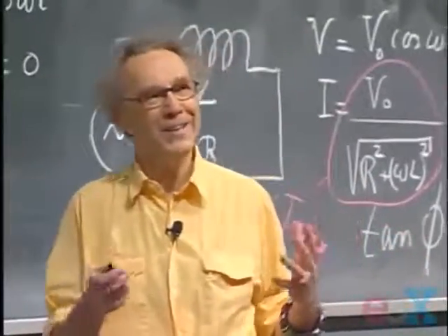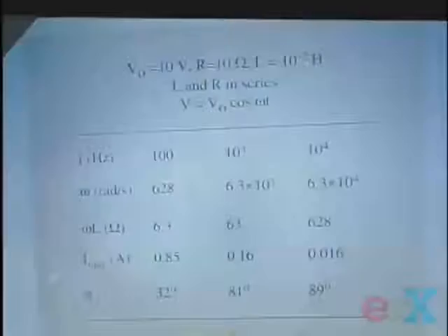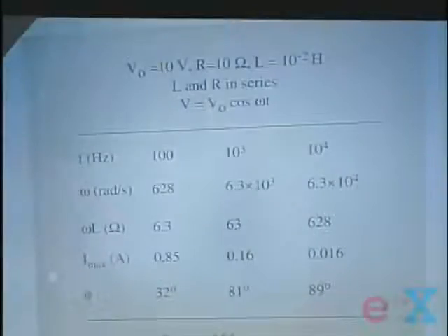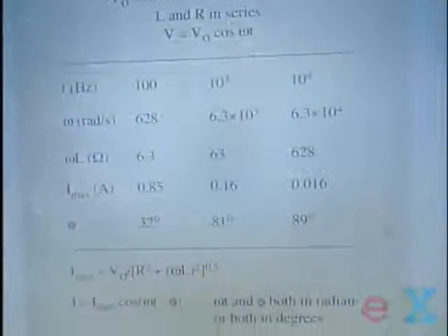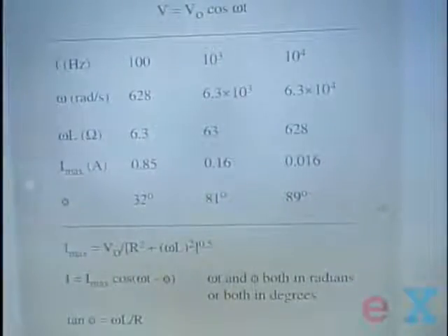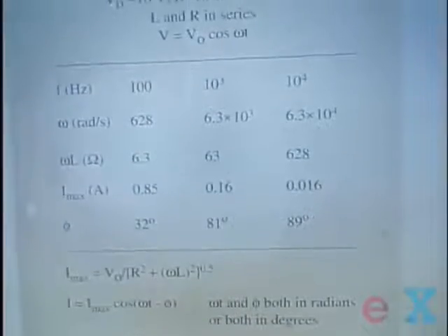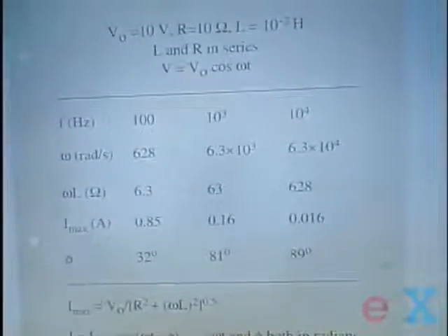So it entirely determines, so to speak, the resistance of that circuit. And so the current that is going to run, at least this is the maximum current, is this value, which we also saw here on the blackboard, that current at high frequency is enormously reduced. It's 50 times lower than this current at low frequency, even though they have the same value for V0. And then you see here the phase angles.